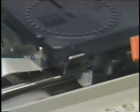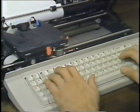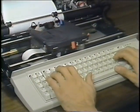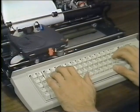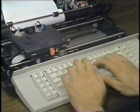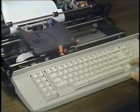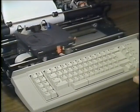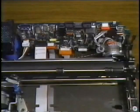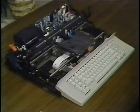The transport motor moves the carrier for tab, carrier return, space, backspace, typing, and correction. The amount of carrier movement for each character depends on the pitch of the print wheel. The printer board determines how far to move the carrier and then drives the transport motor the correct amount to complete the move.